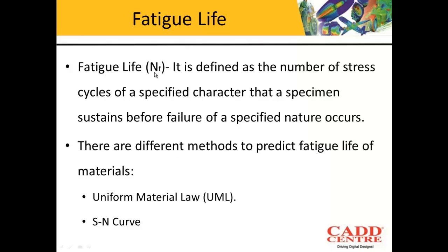Fatigue life, denoted by NF, is defined as the number of stress cycles of a specified character that a specimen sustains before failure of a specified nature occurs. In simpler words, it is nothing but the life cycle of a material. Now, to calculate the fatigue life, there are different methods.